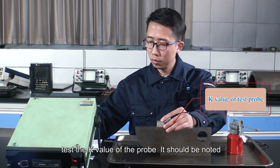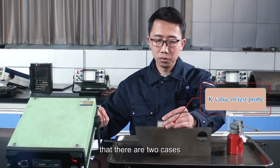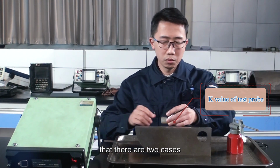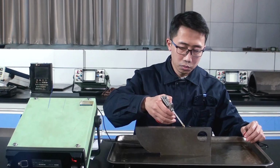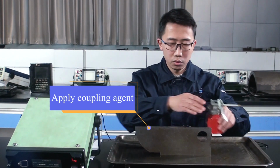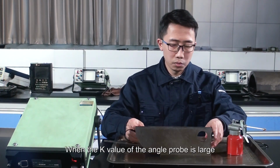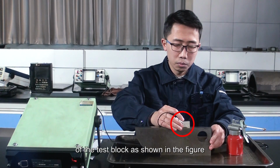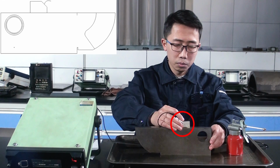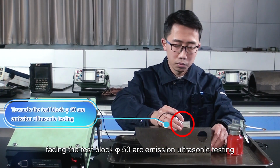Next, test the K value of the probe. It should be noted that there are two cases when measuring the K value. When the K value of the angle probe is large, place the probe on the upper surface of the test block, as shown in the figure, facing the R50 arc, and emit ultrasonic waves for testing.